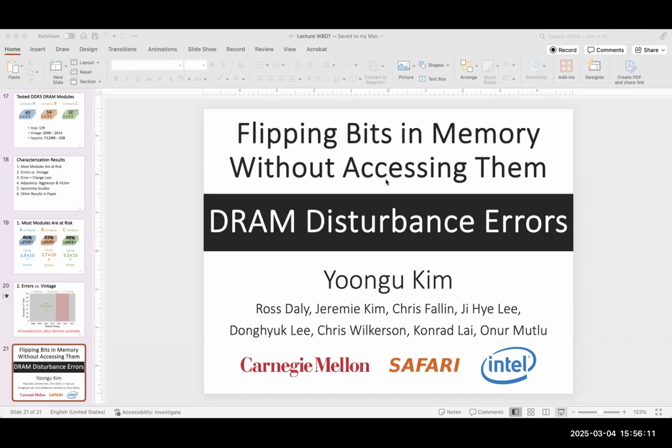Now let's see how we can avoid that situation, so that even if there is some disturbance, we still guarantee that whatever we receive here is still treated as a logic 1. For that, let's say now we consider that our output voltage here was still logic 1, but the voltage value is 3 volt, greater than 2.5, right?